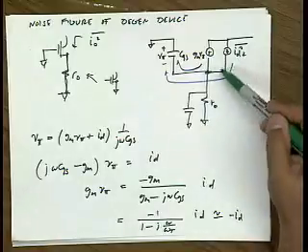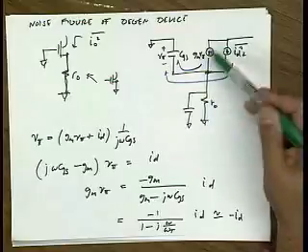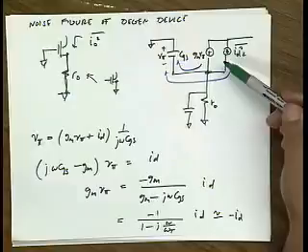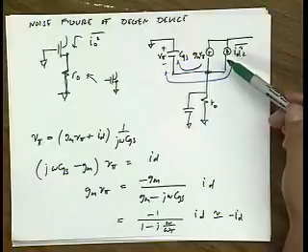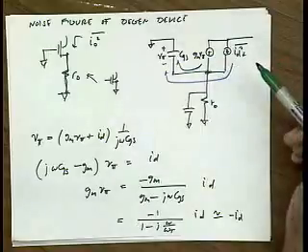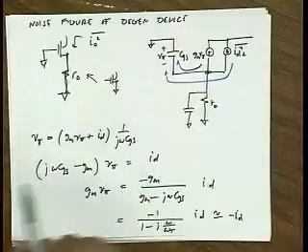almost all the noise of this device flows through this GM generator. So this device contributes nearly no noise at all. If the frequency is really lower than the omega t, then no current goes through CGS. All of it goes through. That's a good point. There's another way to look at it which explains that condition, but let's stick with this for the moment.